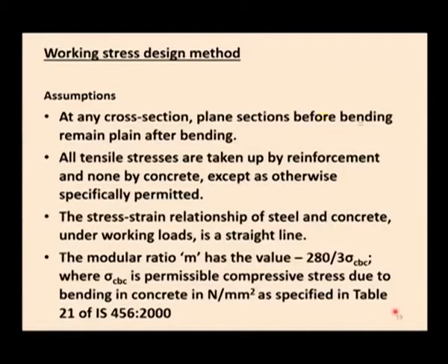So, all the tensile stresses are entirely taken care of by the steel reinforcement and none by the concrete, except otherwise specifically permitted. In some places, concrete is allowed to take certain tensile stresses, for example in the case of water tanks. In some structures only, the concrete will be allowed to take some tensile stresses. Next, the third assumption: the stress strain relationship of steel and concrete under working load is a straight line.